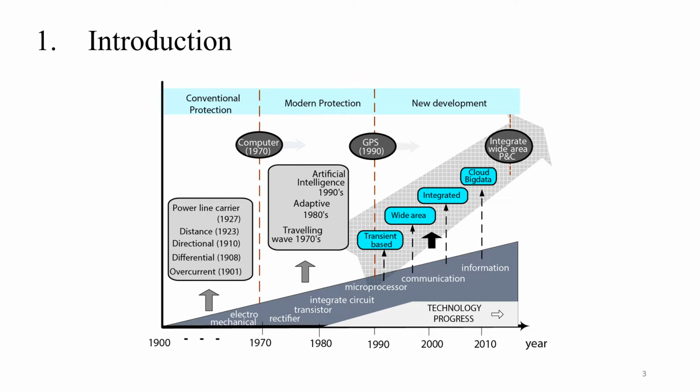During normal operation, the transformer windings and core are subject to a variety of stresses, including vibration, temperature cycling, and expansion and contraction. The magnetic flux causes heating, owing to overload or poor cooling, and there are forces related to fault currents. When the transformer fails, the consequences are generally severe. The transformer may need to be transferred for repair in some situations, depending on its size, which might take a long time.